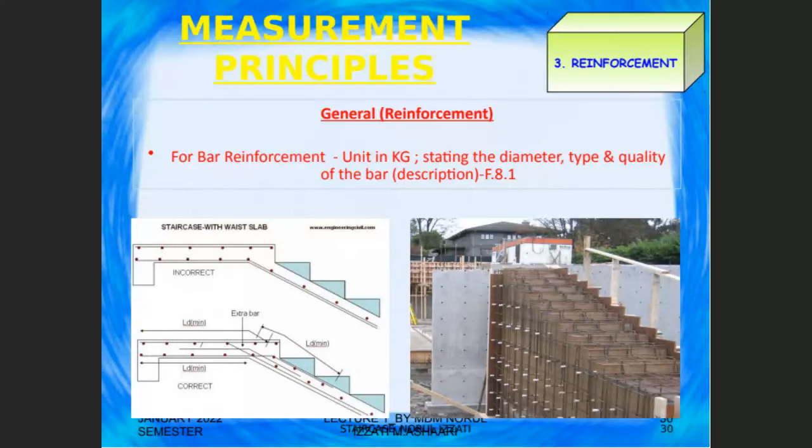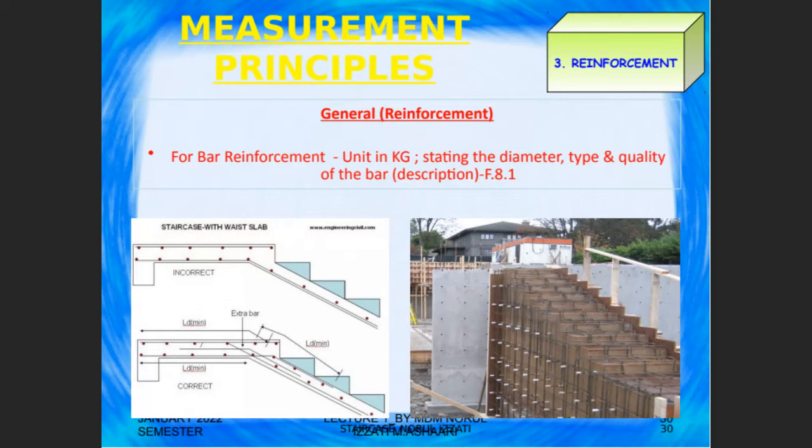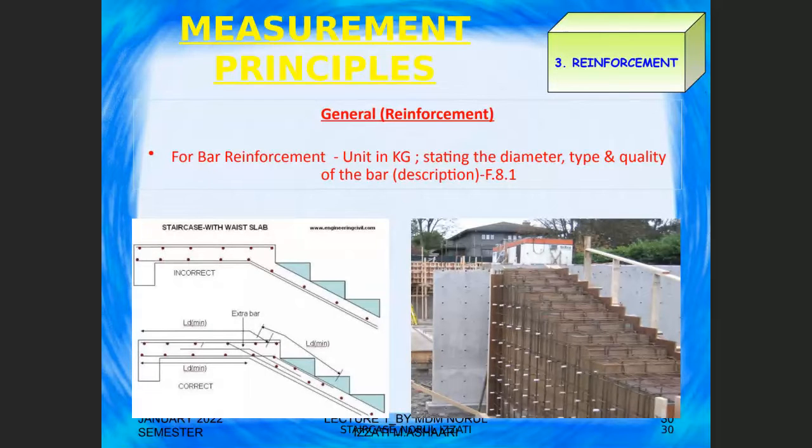Okay, let's continue with the measurement for the bar reinforcement. First, make sure that you have checked the drawing, whether you are given the side view, section view, or the layout plan. This one is very important because you need to know how many bars are available in your drawing. Okay, so the first one, as I did mention, you can refer to F.8.1 in your